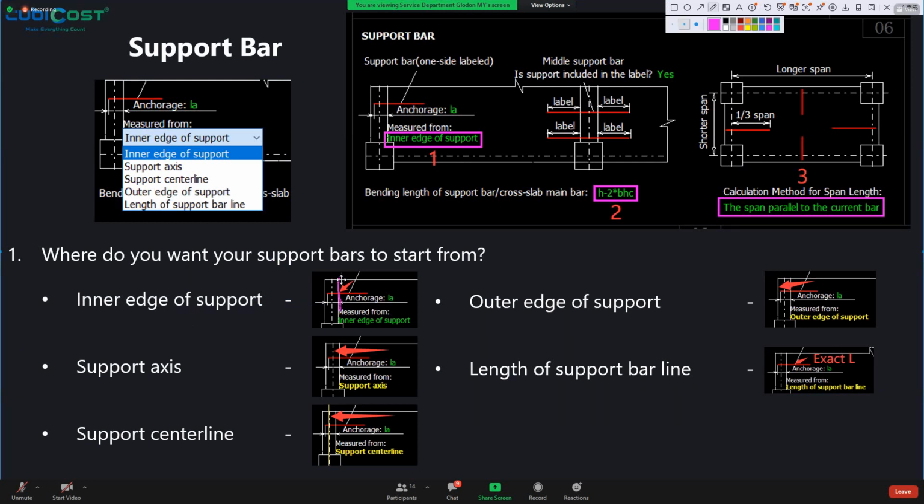Or if you want your slab support bar to start from axis, which means it starts directly from the center point over here, following the axis of the created axis grid line that you have, or support center line, which is also the same as axis, but because the axis just so happens to be at the center of the support, so it follows the axis.